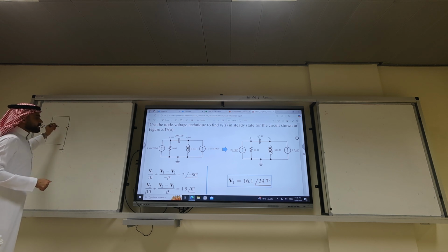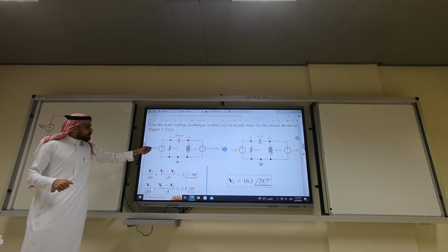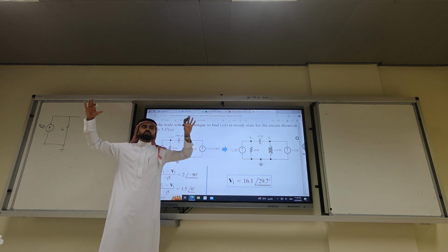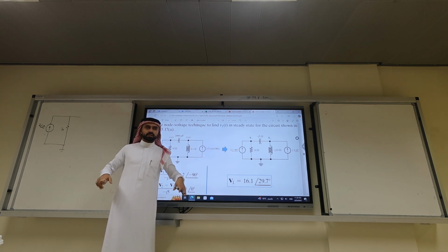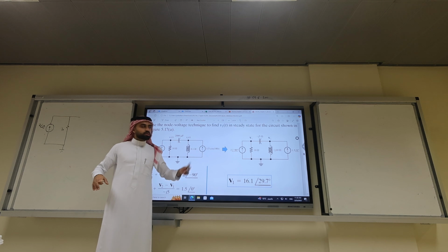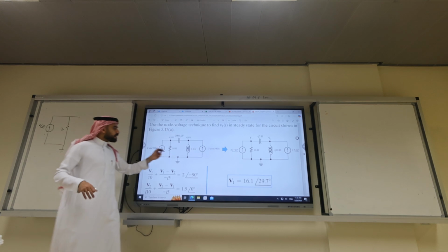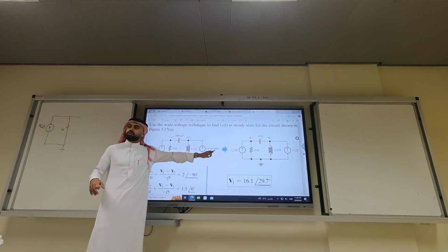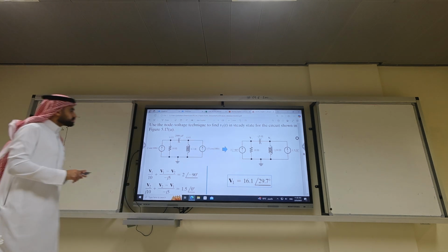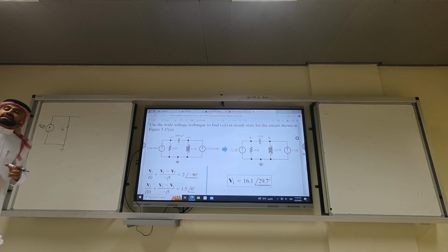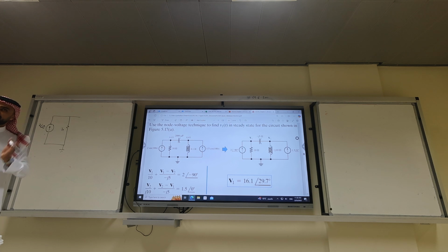The ground, keep the resistor, right? Okay, what's the omega? Omega is the same, 100, 100. You cannot have two voltage sources with two different omegas. The system will oscillate. Doesn't make sense. Get it? So the two current sources have the same omega. You can even combine them to be 2 plus 1.5. It will be 3.5. Well, they're not in phase. They can't combine them. Remember, the sources can be different in phases, but they should have the same frequency.